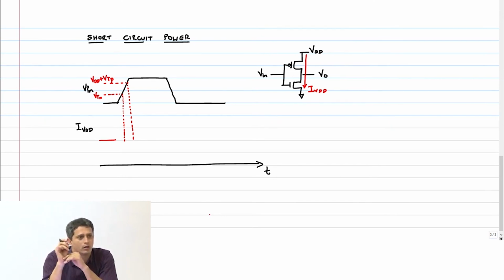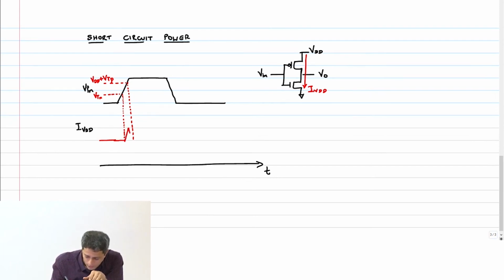What is that point called? Trip point. Vin equal to Vout equal to Vm, right? After that, the PMOS starts going into saturation, NMOS will come into linear, therefore reducing the current, and then back into cutoff. So in this region, you can approximate the current as a triangular region like this, right? And let me call this peak current I peak, IP.